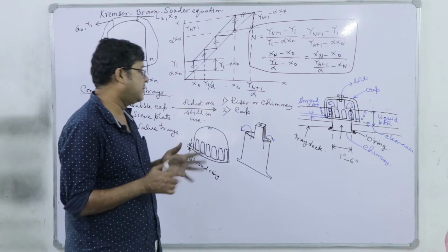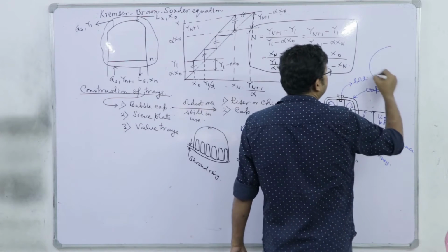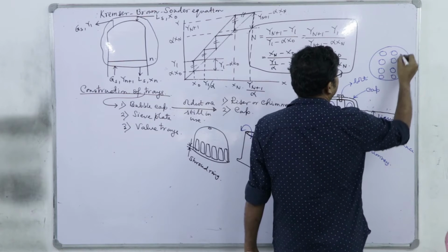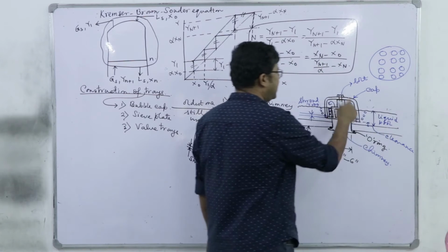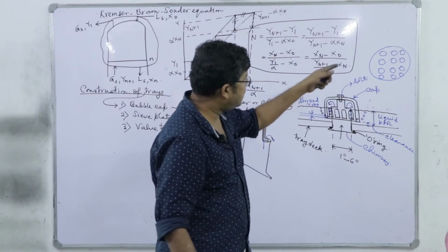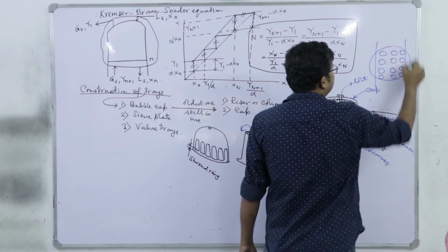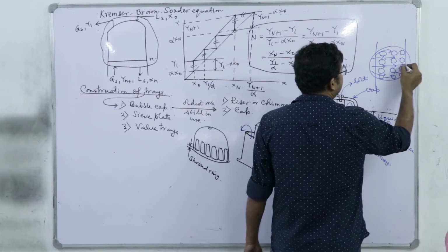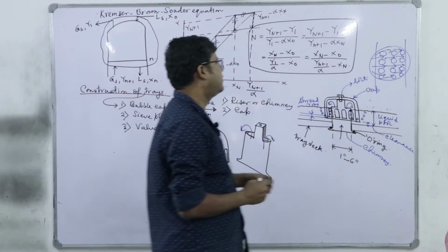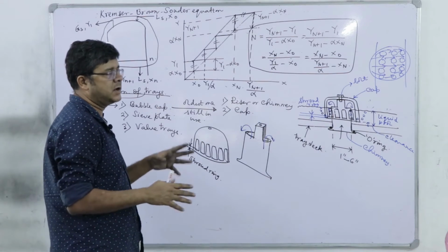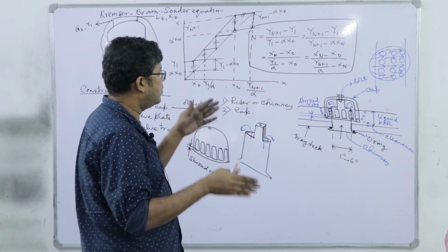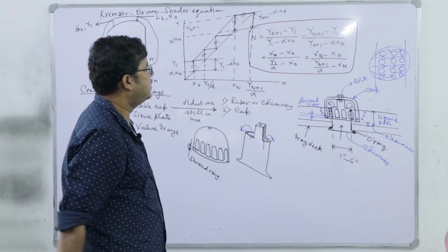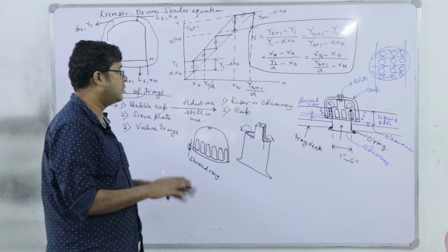However, you see the bubble cap, if you arrange this tray, here we have a bubble cap, here cap, here cap. So it offers high resistance to the flow of liquid. Though it allows a higher residence time, it offers a higher resistance because the liquid has to flow from this side to this side, and the flow is favored by hydraulic gradient. As we have noted, in the design of this tray column, on one side we have the incoming downcomer, on the other side the outgoing downcomer, and to maintain the pool height, we will discuss it. We have the weirs, the downcomers, where one of the walls is extended, right, and it maintains the pool height and hydraulic gradient throughout the tray.